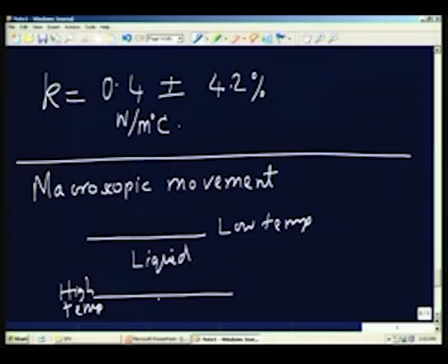Normally at a high temperature the density is smaller, and at low temperature the density is higher, and therefore the liquid will be lighter near the hot wall and it will tend to move up, and then of course the colder liquid will come downwards. So, therefore, you expect some kind of a motion like this, up and down motion. So, this is referred to as natural convection.